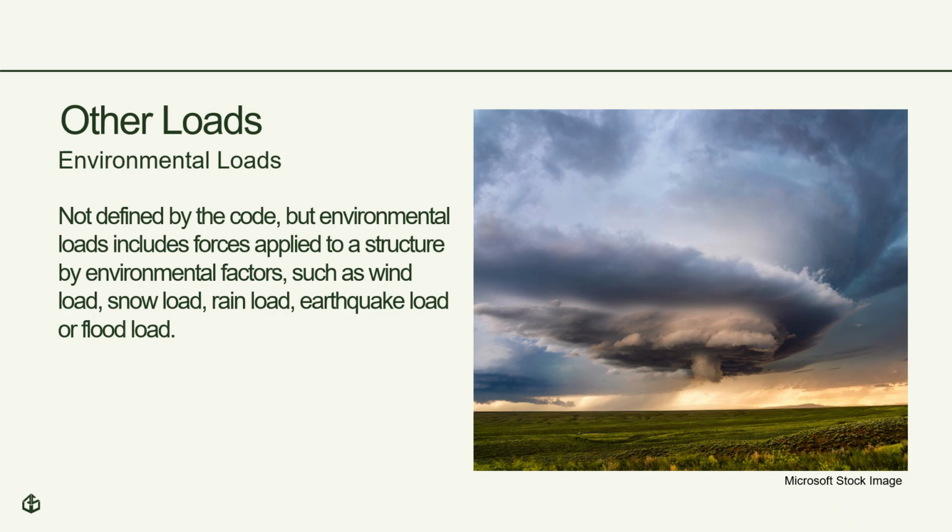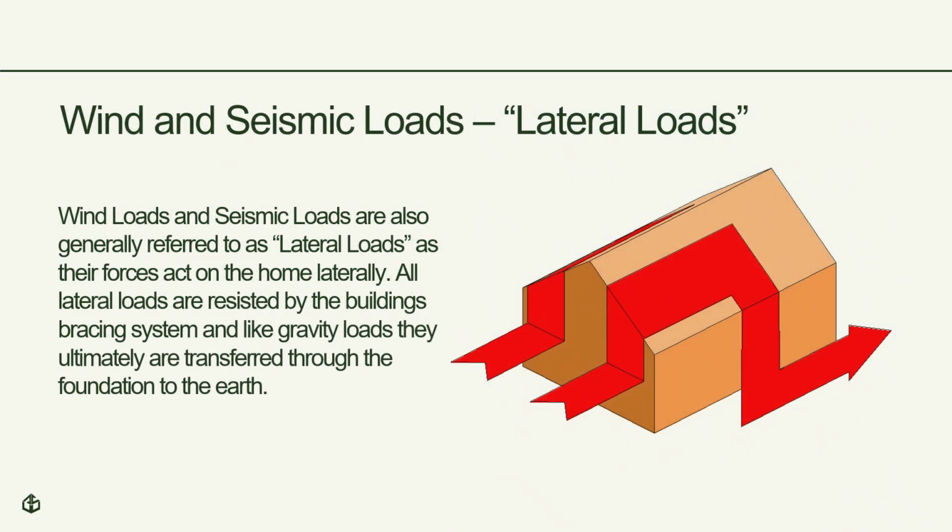While not defined by the IRC, environmental loads are forces applied to the structure by environmental factors. Wind, snow, rain, earthquake, floods, essentially Mother Nature. Wind and seismic loads are also commonly referred to as lateral loads, as their force acts on the house laterally. Like gravity loads, all of those loads transfer down through the building and ultimately to the earth.